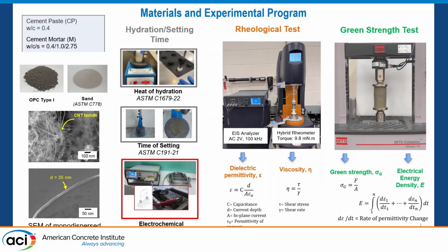And also we evaluated the green strength of the material after the initial setting by conducting uniaxial compression tests. And for all these experiments, we use the dielectric permittivity data to see if there is any correlation between the time of setting, rheology, viscosity, and green strength, and electrical data.